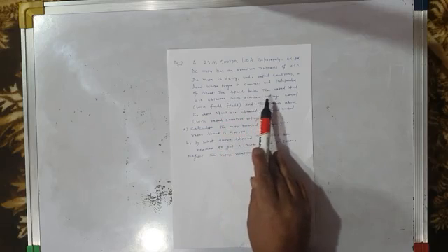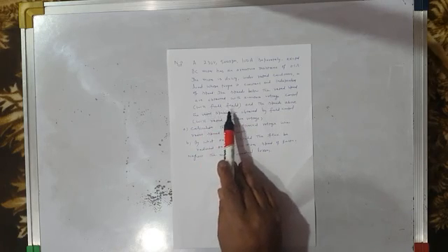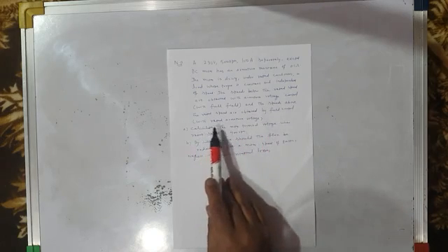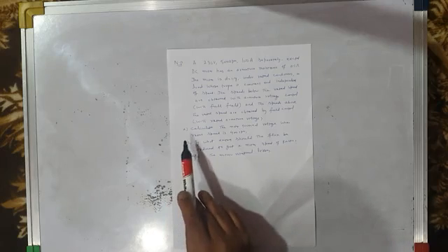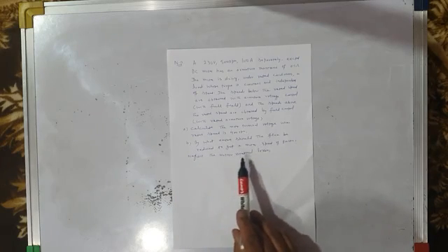The speeds below the rated speed are obtained with armature voltage control with full field, and the speeds above rated speed are obtained by field control with rated armature voltage. Part A. Calculate the motor terminal voltage when the speed is 400 rpm. Part B. By what amount should the flux be reduced to get a motor speed of 800 rpm? Neglect the motor's rotational losses.